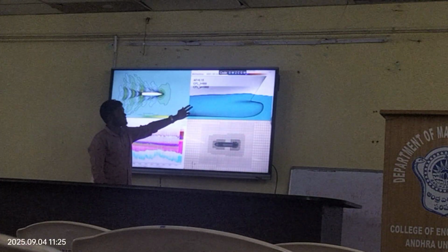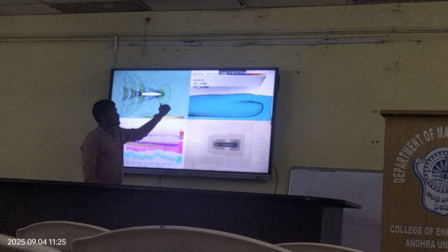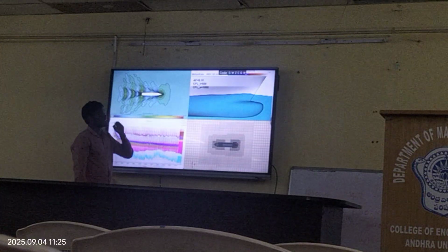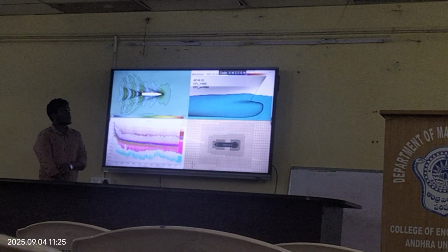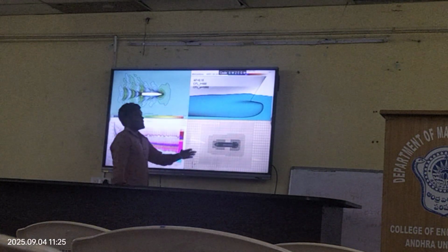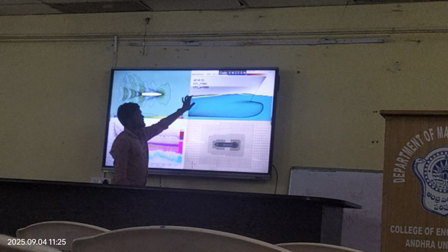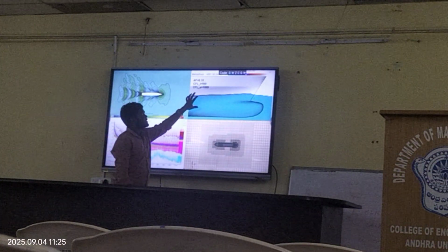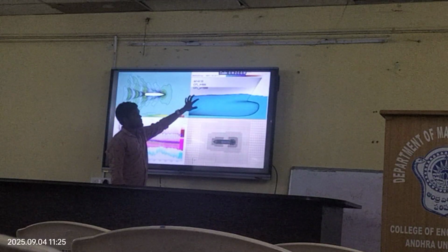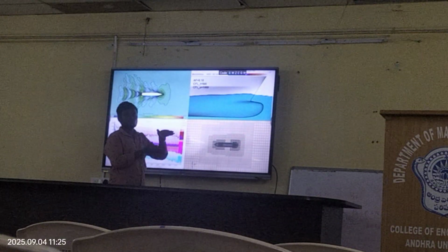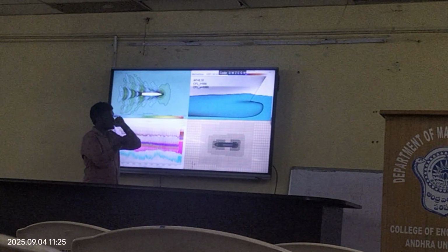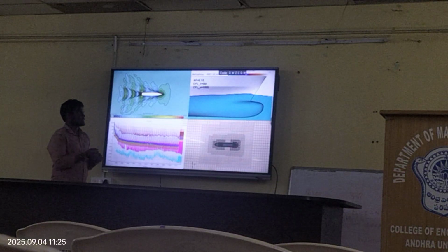This is the volume fraction. By this, we decide how much of the bow is immersed in water or emerged. At this area we can see some color change and variation. This is nothing but the free surface. At this area much resistance is offered to the ship as it goes through two multi-physics domains, that is, air and water.